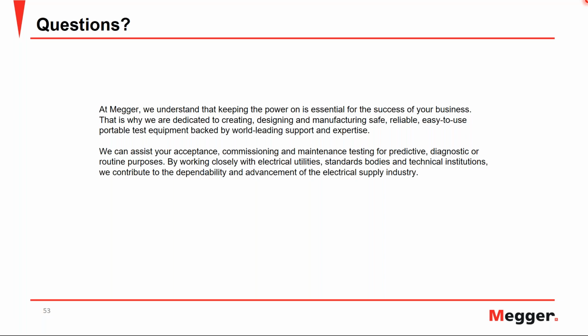One thing I would like to mention is that natural ester, FR3 or any other such oil, is more polar in nature, and because of that, your power factor values are going to be higher for any transformer that has natural ester oil in it. And slide number 30 that Charles showed, IEEE C57.152, does talk about the limits for the different voltage classes, and what the values would be if you have natural ester oil.